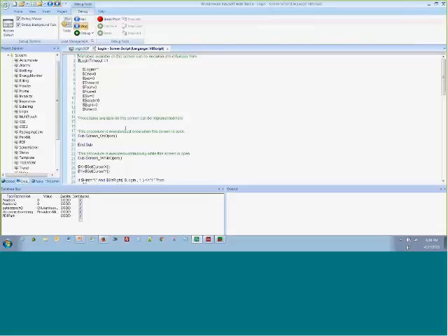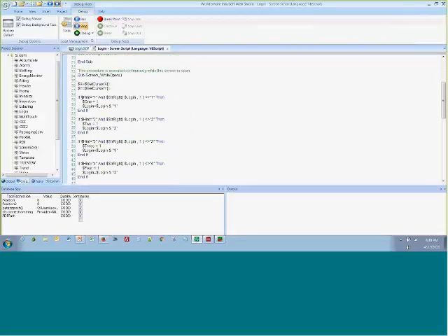Now, the script behind the scenes here works on the idea of when you get the hint, it checks to see, okay, if the hint is 1, and I'm not a VBScript programmer, so this code might be absolutely horribly put together, but it also does a comparison on, is the rightmost character of the login password that you've typed in already a 1? Now, this is preventing duplicates so that you can't drag your finger around on the same button over and over again. So it says as long as it's not a 1, then take the login tag and append the number 1 to it.